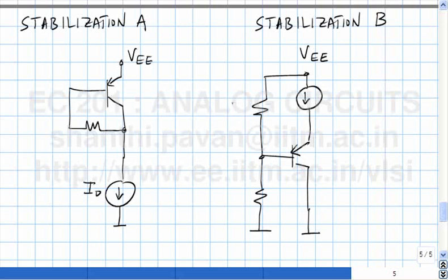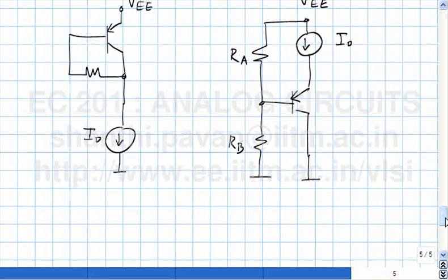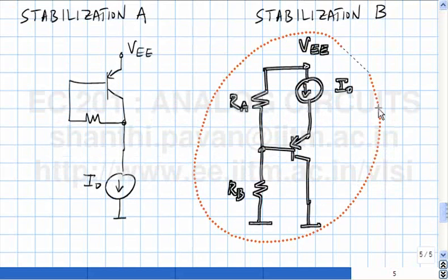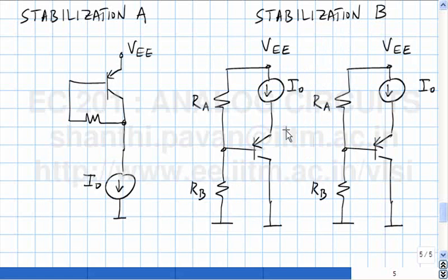And this resistor string biases the base to some potential. Okay, so this is I naught. And a poorer cousin of this technique is what? Replace the current source with a large resistor. And what is the definition of large?